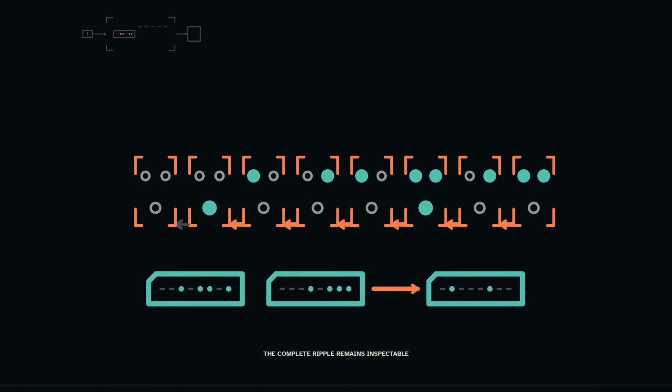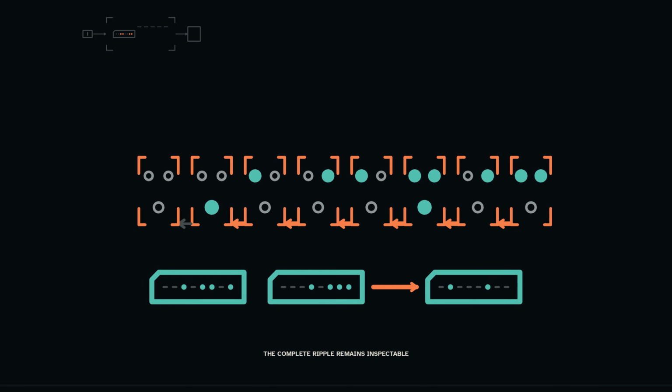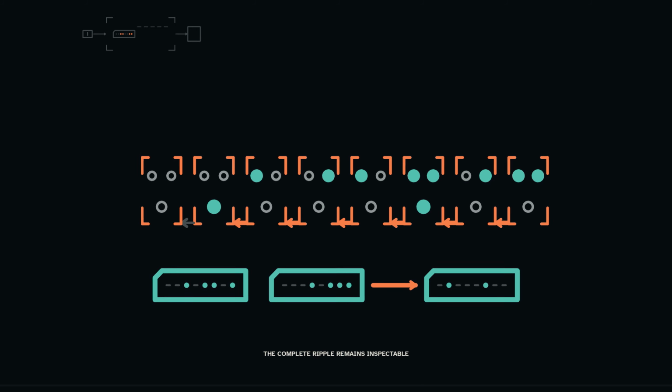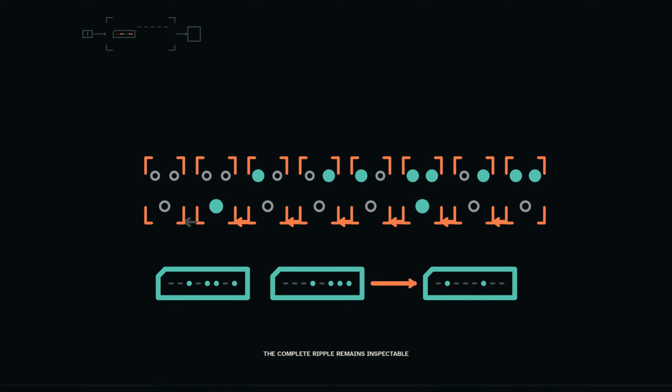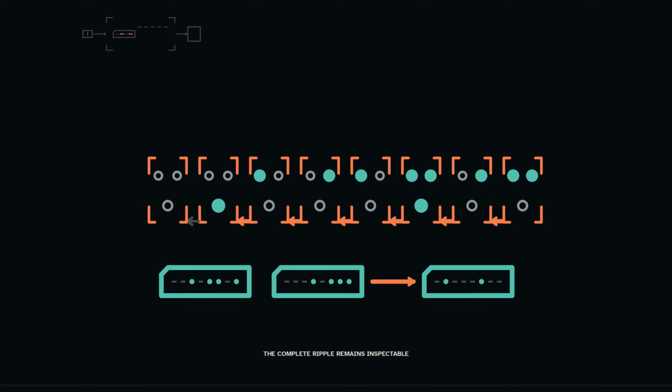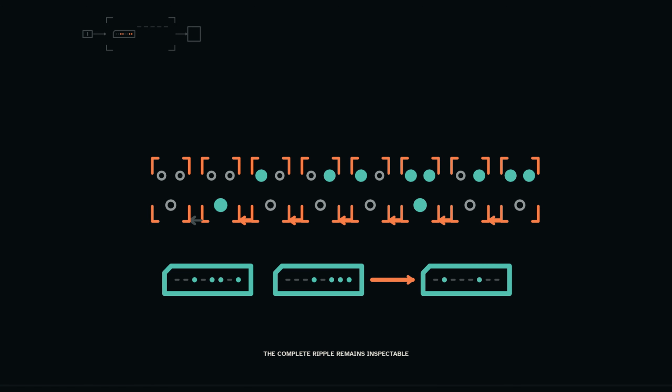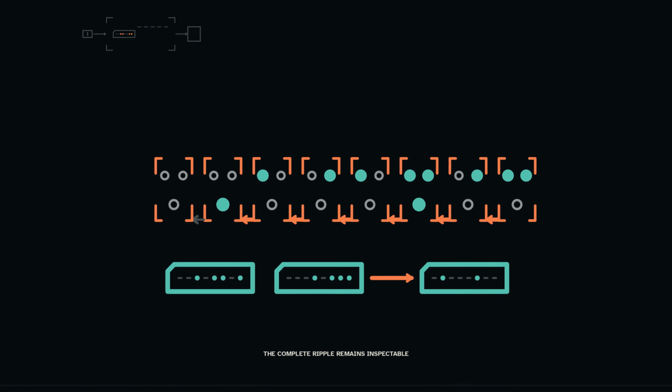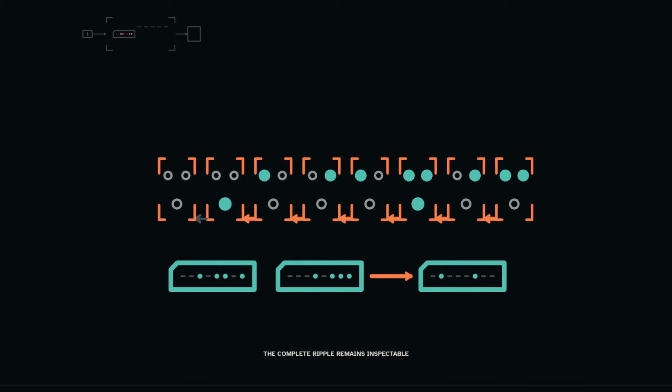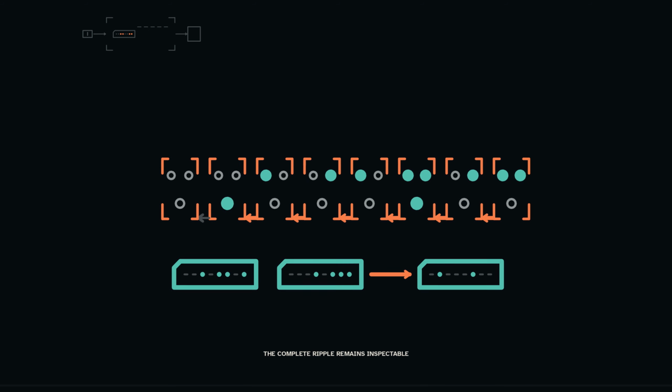Signed overflow requires another test: whether the signs of the operands and result are inconsistent for 2's complement addition. The adder produces bit results and carries. Surrounding flag logic preserves the selected summaries. Arithmetic meaning remains a contract over these patterns, not a new physical substance inside the cells.